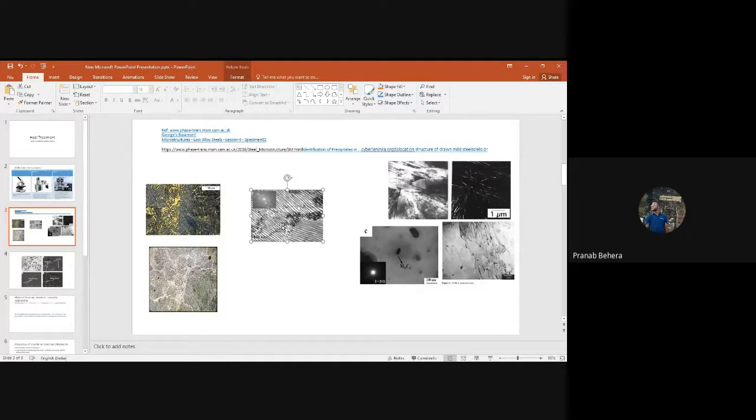Okay, can you people tell me what this image is showing? This is a scanning electron microscope image. What is this? Again a pearlitic structure, right? Alternate layers of ferrite and cementite, darker and lighter. But can you people tell me why there is such a difference? What is the difference between them?